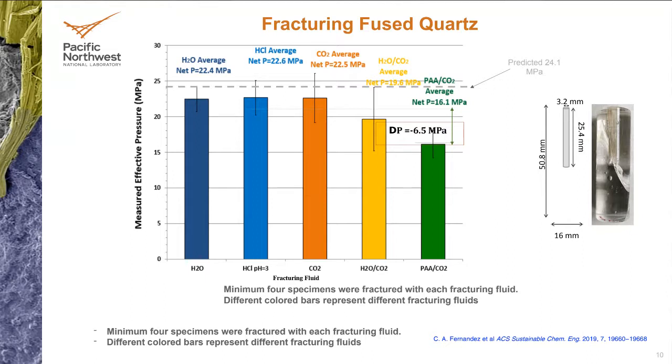So what we propose here is, okay, if we're fracturing at lower pressures, but the system is open, the only way is that, if we're measuring lower values of pressure, maybe we have a shell formed that plugs this wellbore and generates some radial stress that the pump, several feet away from this rock, doesn't see.